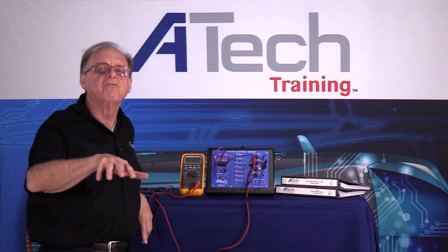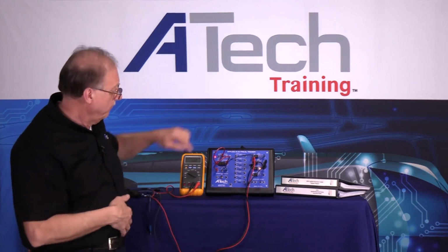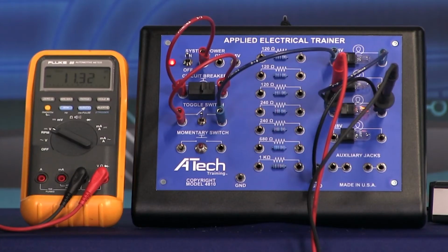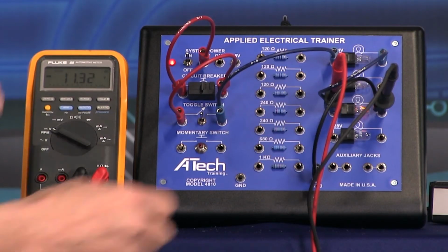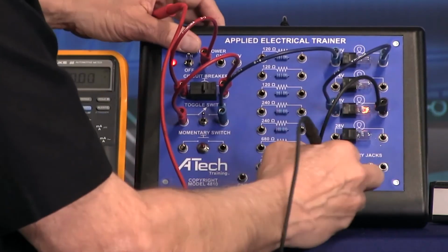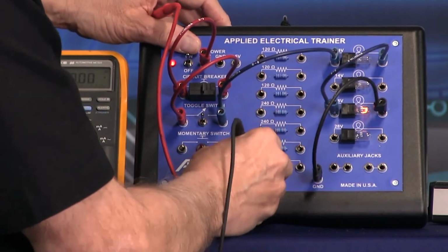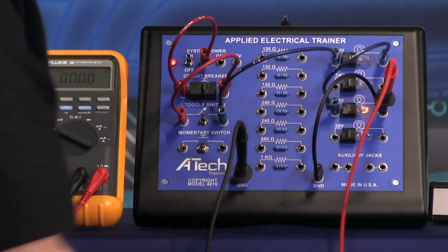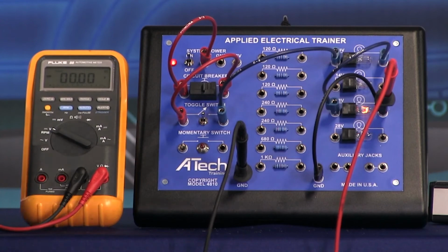That would be like an additional load in the circuit. In other words, this would be resistance that we came up and showed. So I have a voltage drop of 11.32 and I had 6 over there. So again, if I take my red lead and my black lead and move them across, there's no voltage on the ground. So I used up all the energy.